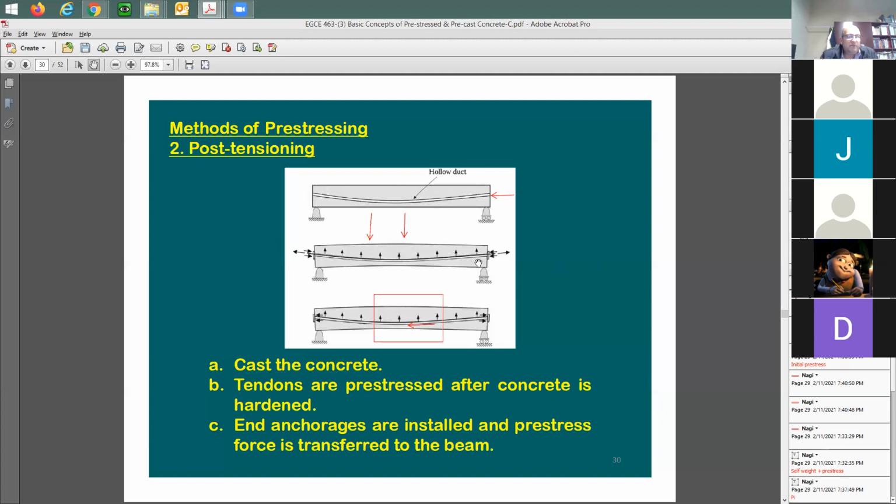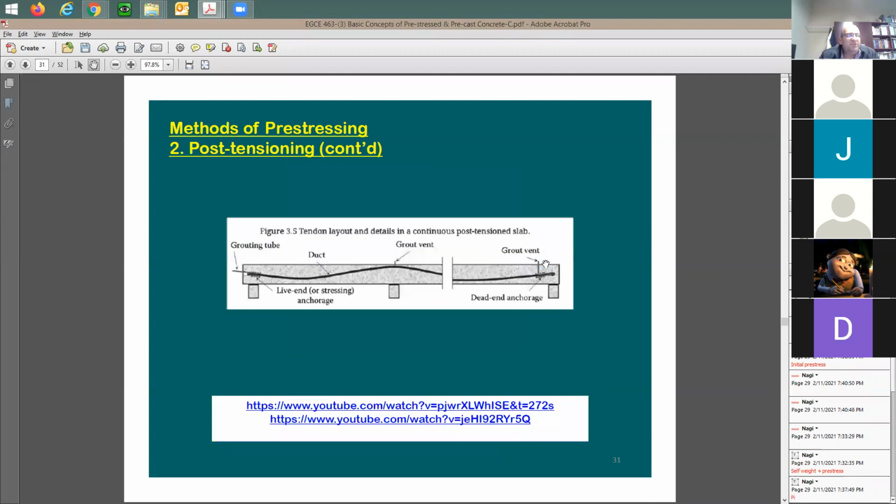This pre-stress force is going to be acting on the beam very similar to the loads, right? Just imagine that you put this upside down. It means you're going to be pushing the beam in this direction, and the load is also going to be pushing in the same direction. So you're going to be breaking the beam quickly. There's no resistance. There is really no use of the pre-stress in this case. Look at the deforming shape when it comes to continuous beams. It's going to look like this. Just look at any deforming beam, and it's going to look exactly like this.